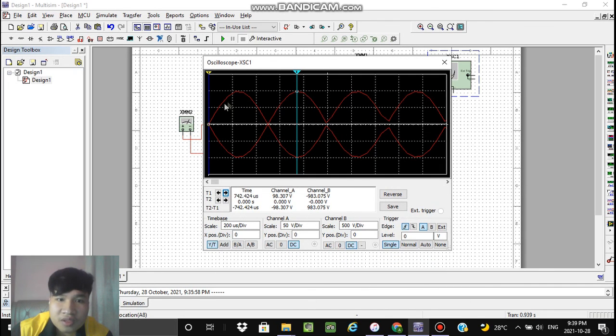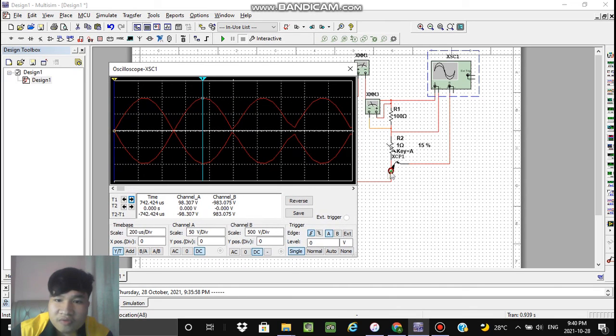And from the graph here, this is a sine graph and it's on the positive side because the bridge rectifier converts AC to DC. Even the VAC negative source part is in the positive part. Next is channel B, which we have down here. This channel B resembles a sine wave as well. This represents the inverted current output that we obtain from the clamp that we reverse connected here.